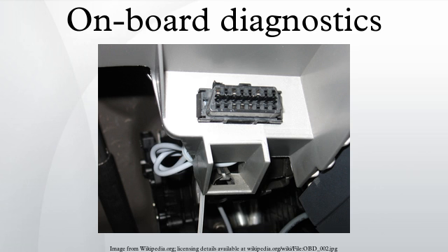Cadillac fuel-injected vehicles are equipped with actual onboard diagnostics, providing trouble codes, actuator tests and sensor data through the new digital electronic climate control display. Holding down off and warmer for several seconds activates the diagnostic mode without the need for an external scan tool.